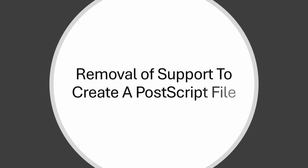And then the removal of support to create a PostScript file. The PSOUT command has been completely removed, and the export command no longer supports the ability to export to this format. So if you need to create a PostScript file from the drawing, they say to configure a PC3 file according to the output needed. So that would be the main changes in that.